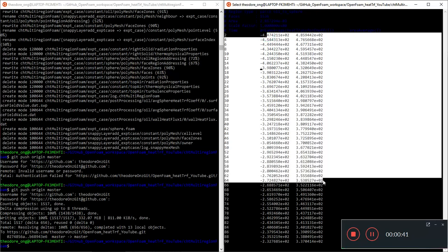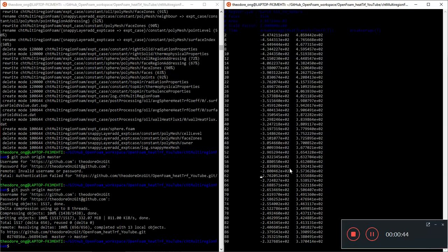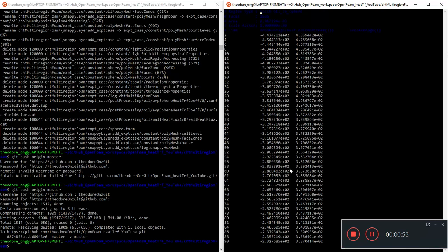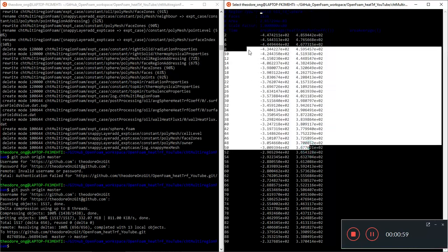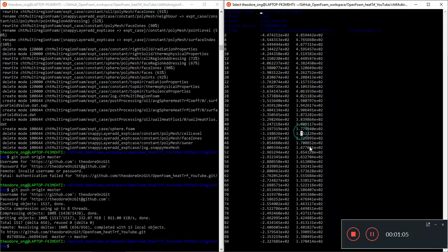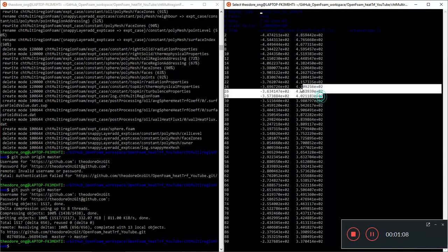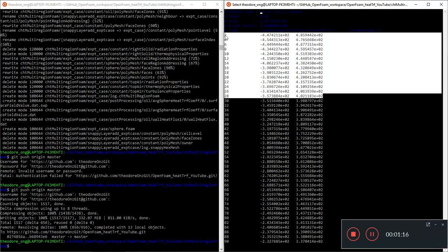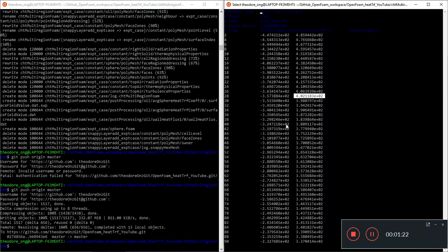heat transfer coefficient results against temperature and trying to get the Nusselt number and Rayleigh number out. Of course, we want to compare that against the empirical correlation. Do keep in mind, this is just using a laminar model. There is no turbulence model in it yet, despite the Rayleigh number being pretty much in the turbulence zone for at least the first 30 seconds, because in this simulation we have a temperature of about 400 Kelvin at 28 seconds.